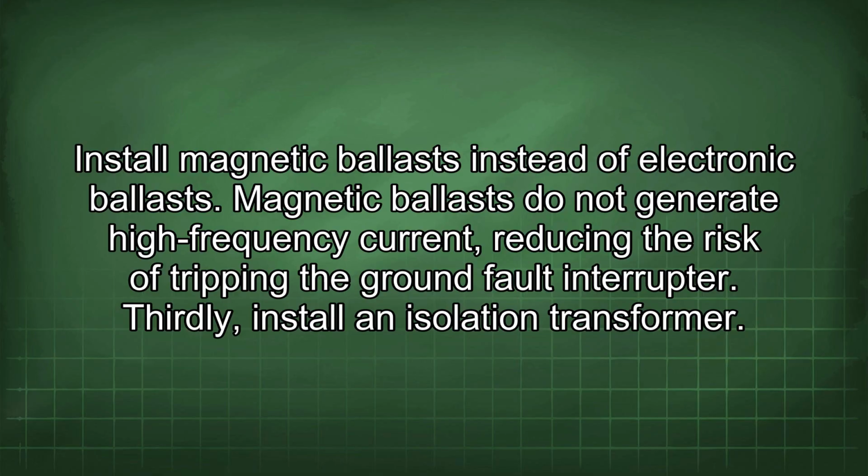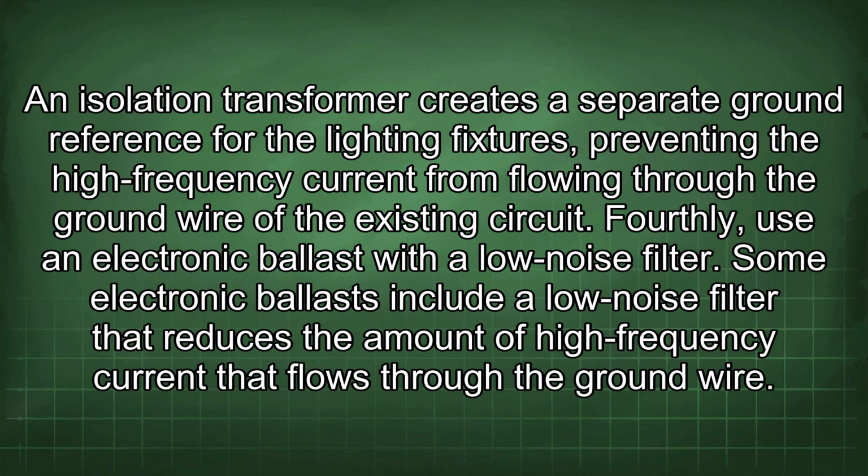Thirdly, install an isolation transformer. An isolation transformer creates a separate ground reference for the lighting fixtures, preventing the high-frequency current from flowing through the ground wire of the existing circuit.